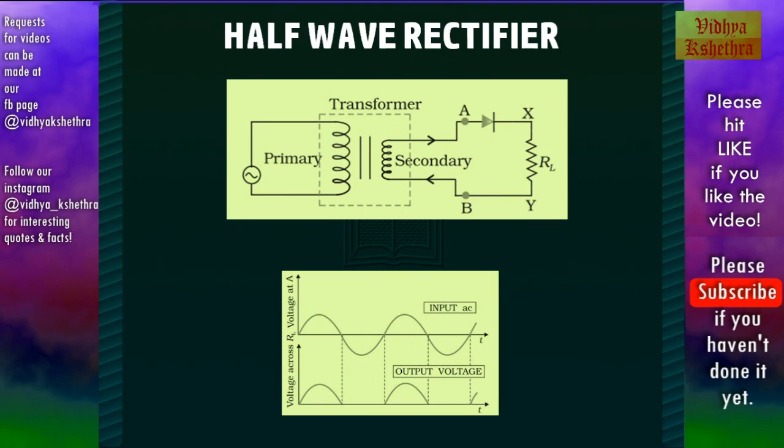Now these graphs show the input AC as well as the output voltage. As we can see, only half of the wave we get as output across R, while the negative part of the AC is removed. This is known as a half-wave rectifier.